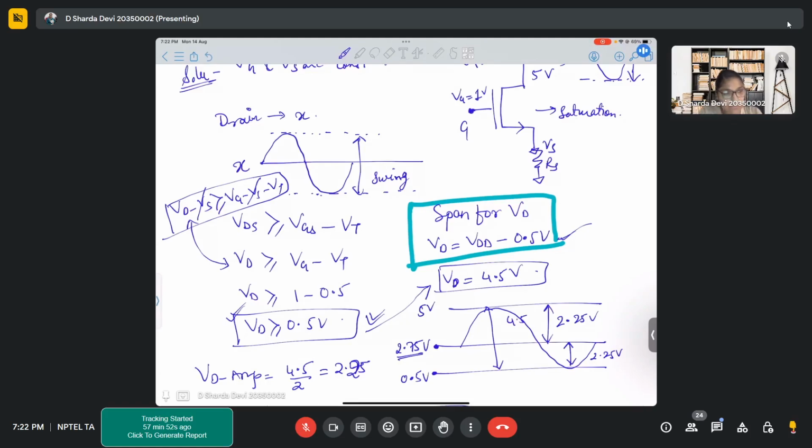Variability in ID. I'll tell you what. You can get very high gain, but your transistor may not be in saturation. And I'll tell you where. When you are in the subthreshold region, you will get very high gain, like it's too high. But you cannot have your amplifiers designed in a subthreshold region. Why? Because the subthreshold region is not stable. It is metastable, so any moment it can switch between on and off.